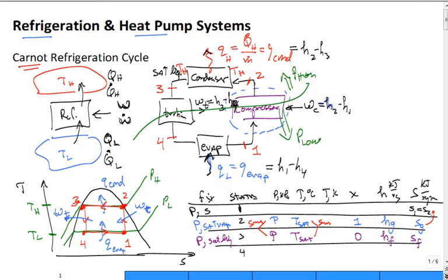How? Well, conceptually, I did a second law analysis. There's no heat transfer. There's no irreversibility. It's a perfect compressor. Boom. Isentropic compression. And what about this pressure? Well, this is the high pressure, and this is the low pressure in the evaporator. So how do I find the enthalpy and the temperature for state 1?